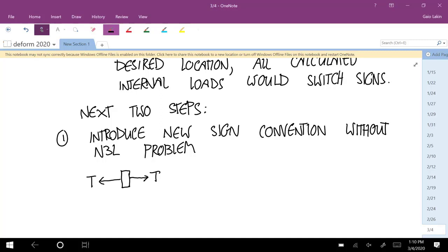How many internal loads did we have to deal with, remember? 4, yep. So we had to deal with the x component of the force, the y component of the force, the x component of the couple, and the z component of the couple. So I'm just going to go through all 4 of those. The other force, so this is tension, compression. If it's negative, it's compression. So tension would be positive, compression would be negative.